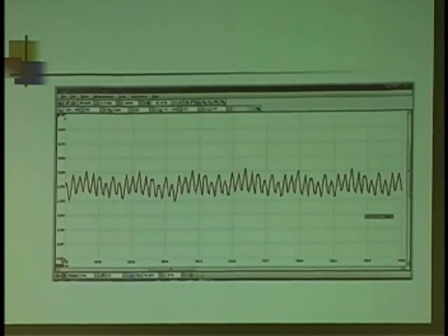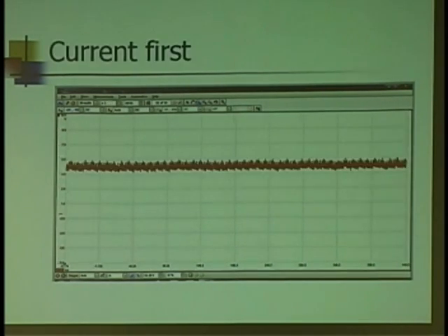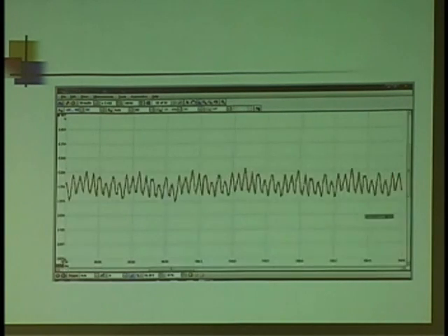Is there an AC component to the DC voltage coming out of the alternator? Sure there is. So it's not going to be unusual when I'm zooming in this close. Notice you don't see it so much here, but when I start zooming in, I'm going to notice that. And that's all I'm seeing, the AC influence on the DC voltage to the fuel pump. Okay?